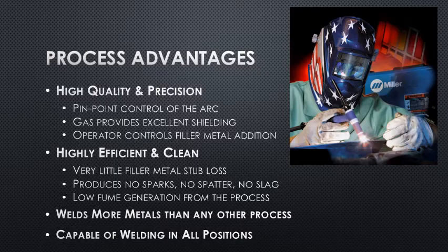The process produces no sparks, no spatter, no slag, has very low fume generation, and as a result, most of what you pay for goes into the work, and you don't have to deal with a lot of the other issues that you would normally encounter with a consumable electrode process like gas metal arc or MIG welding, and of course shielded metal arc or stick welding, which tend to produce significant amount of spatter, smoke, and even slag.